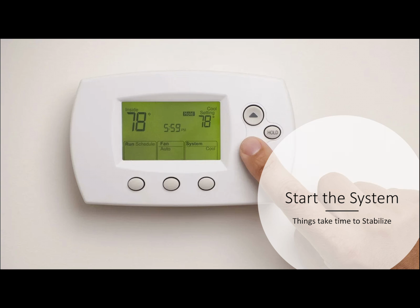So we're at the point now where we've got our probes deployed. We want to simply turn it to cool and turn on the system. And you've got to remember, as soon as you turn that air conditioner on, it's not doing any cooling, right? The second it turns on, the temperature split is basically zero, and as it runs longer and longer, the temperature split gets to its maximum.